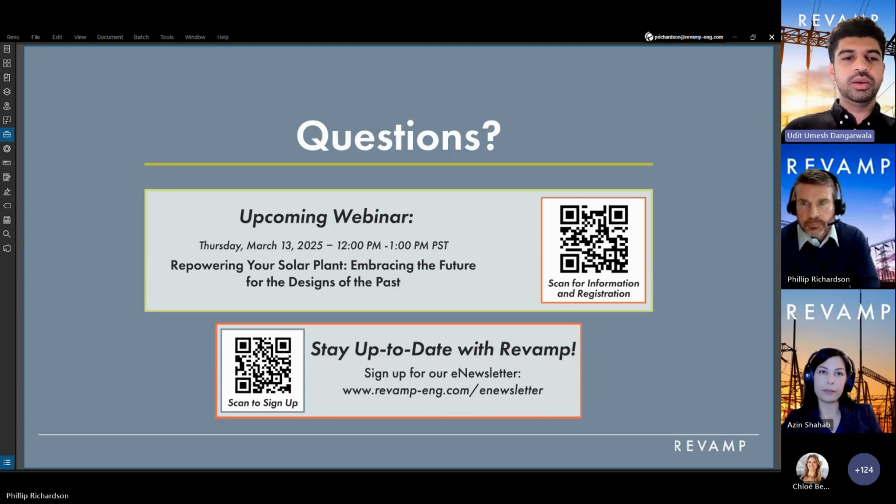The fuses typically will not clear an arcing fault at the combiner box. And as a result, fault clearing time would not be able to be determined in a software. So that's why the provision in NFPA 70E comes in handy. The 2-second guidance that is provided is based on the time to react when an arcing fault is seen. So 2 seconds is enough for a person to react and move away from the arcing region. So yes, we can definitely use the 2-second rule to determine the incident energy at combiner boxes.